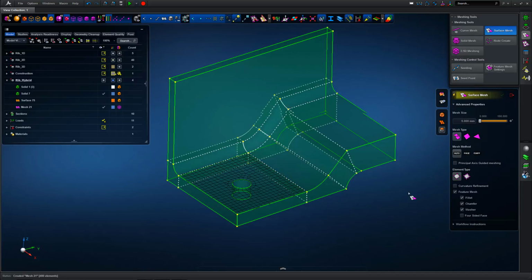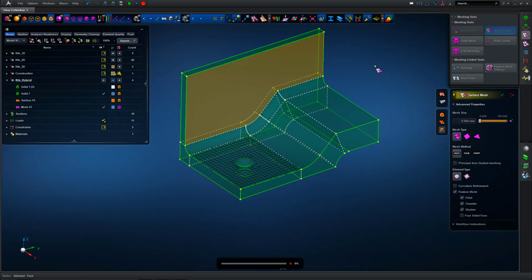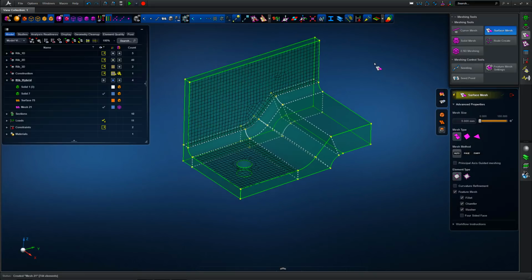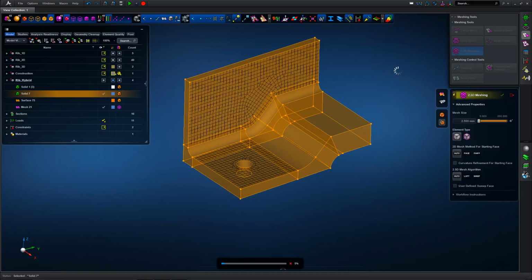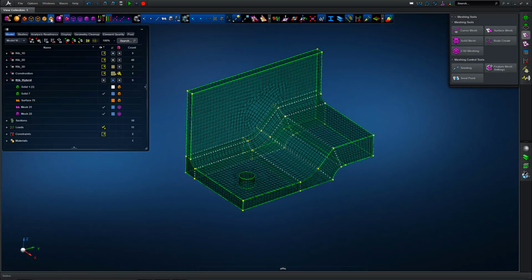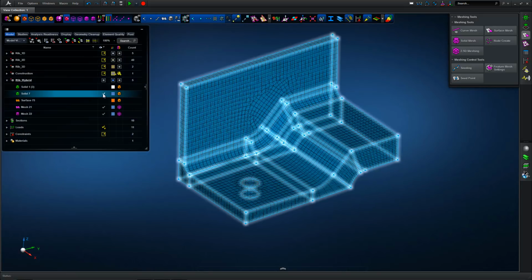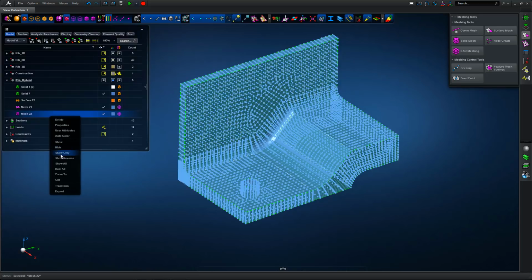What we can do is use the 2D surface mesher as a surface seed to control the underlying hex mesh. So a couple of these faces where we saw potentially skewed elements. With those seed surfaces or seed meshes defined, we can go back into the 2D meshing, repeat the hex meshing process, and then we can double check the mesh as required.